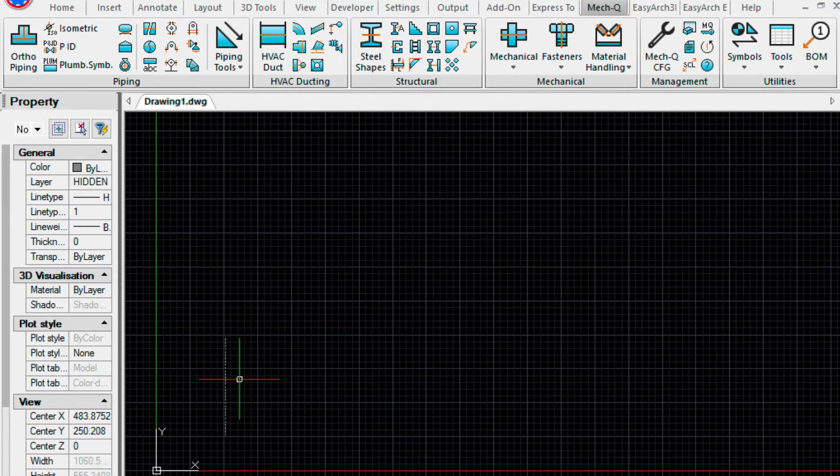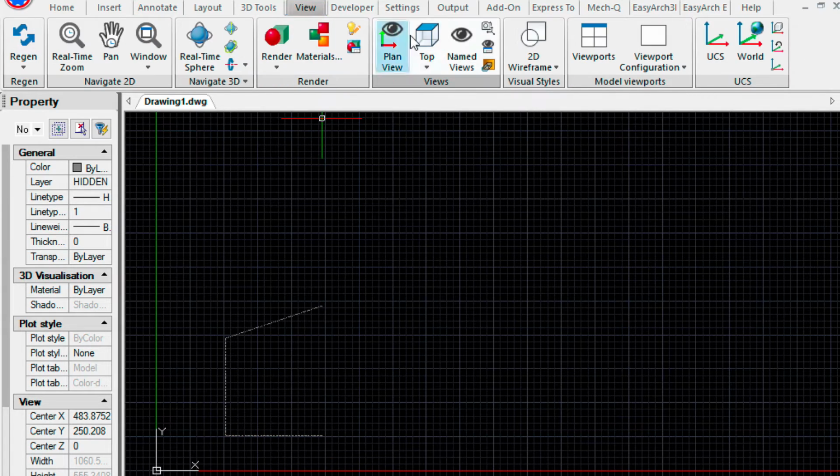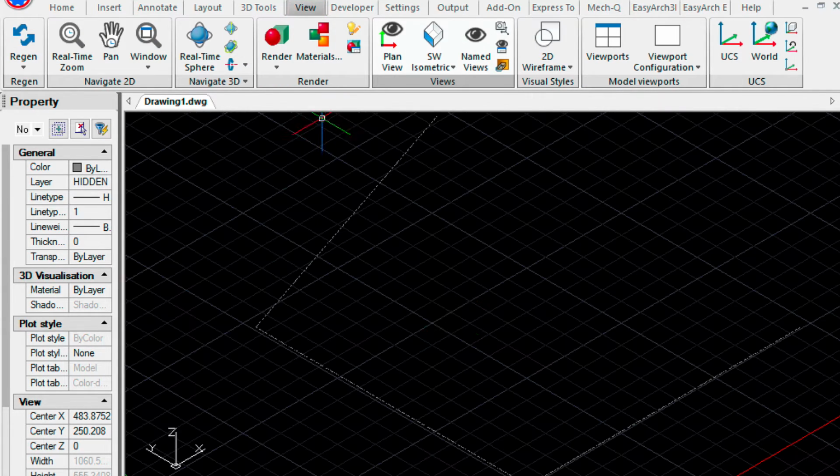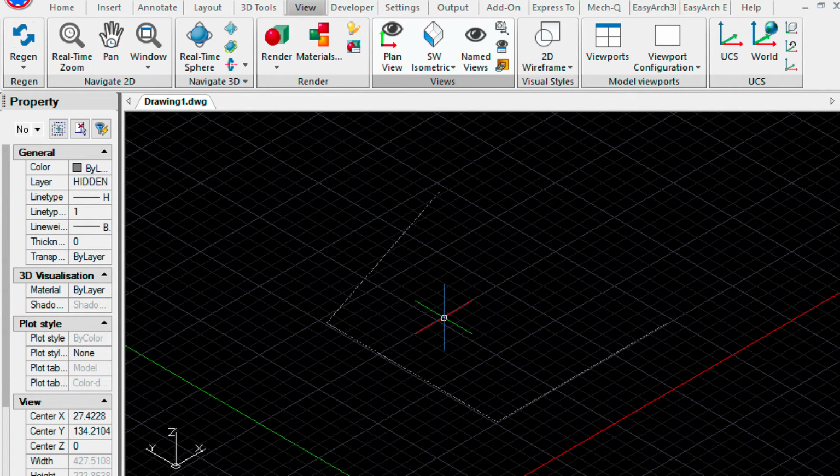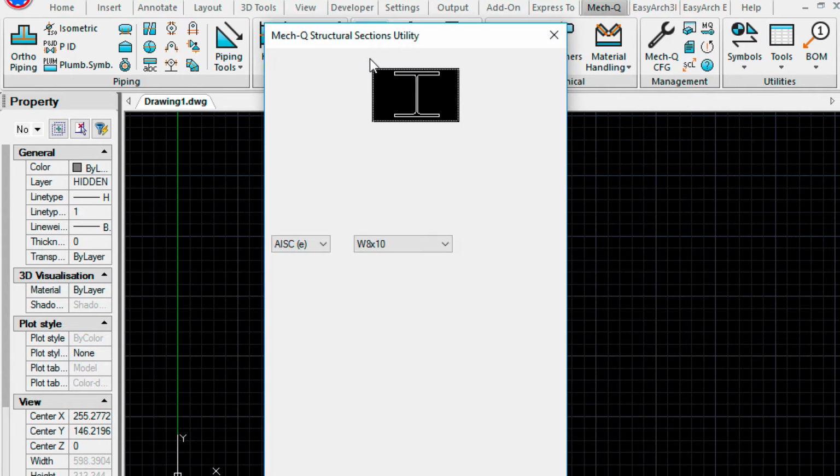And then we're going to create a roof line going over at 12 feet, comma, 4 feet to get our 4/12 slope. And then at the bottom, we'll draw a line which we'll use later as our reference point and our ground level rotation reference point. So here's what it looks like, and you can see the roof there.